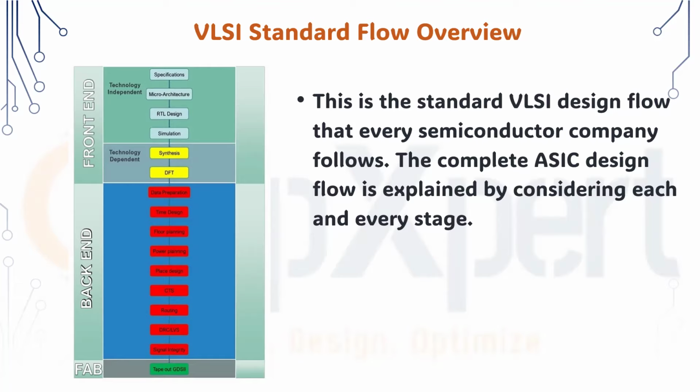So the backend team will do the timing analysis: how much speed the chip has to work at, and how the data has to be ready for each of the inputs required. And then the floor planning. Floor planning is the process where they plan the placement of the RAMs, analog macros, digital to analog converters and PLLs. All this they will place in the right directions. Likewise, we'll cover each of the steps in detail in this backend. Okay, let's go to the next step and we'll cover each step in detail.